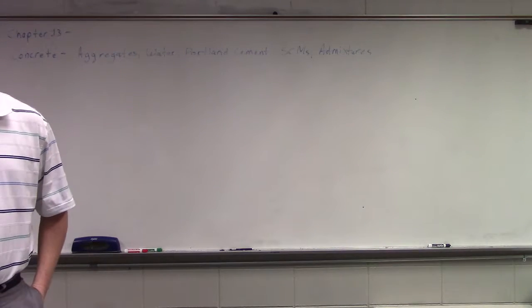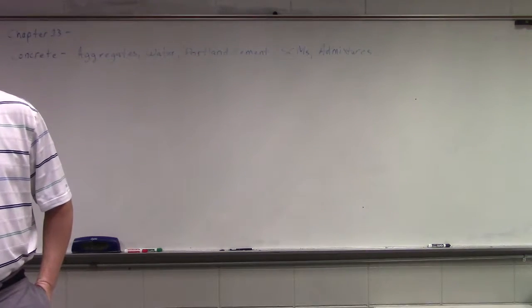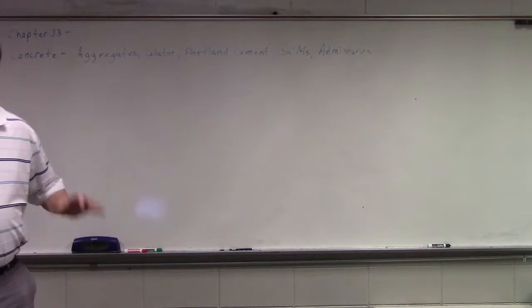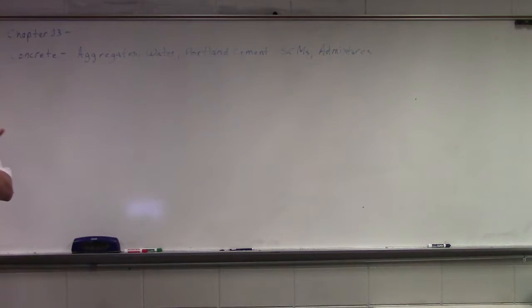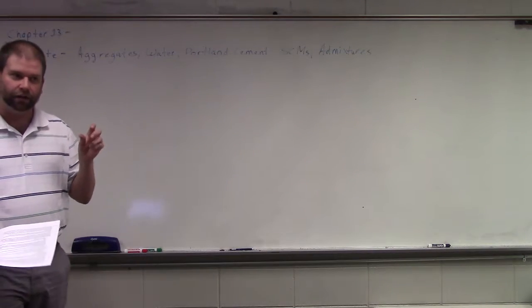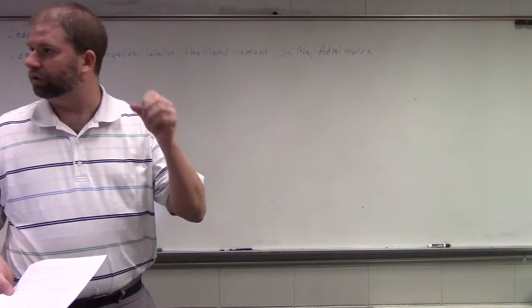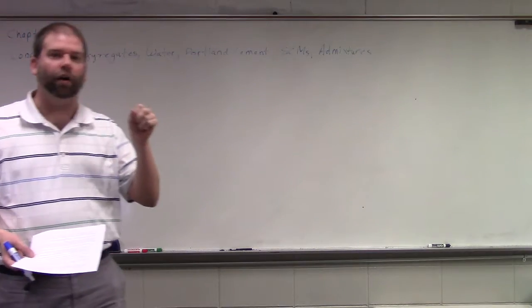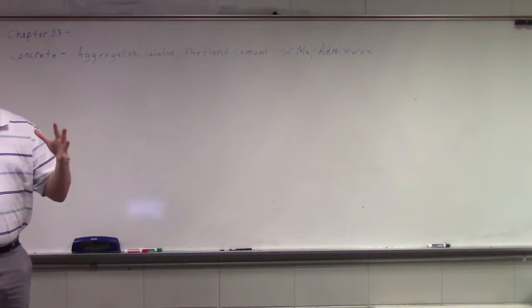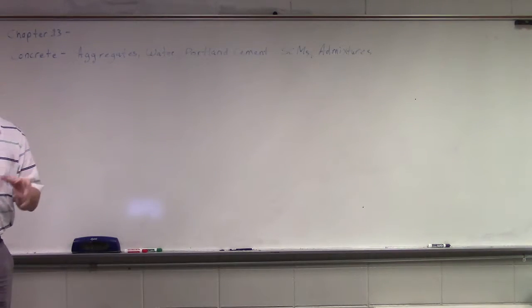It's still a fairly involved process to figure out our tensile reinforcement, so just be aware that there is also compressive reinforcement that's used because steel has a fairly high strength to area ratio. So you can get a lot of compressive strength for a small area where we need a larger bulk volume from our concrete.